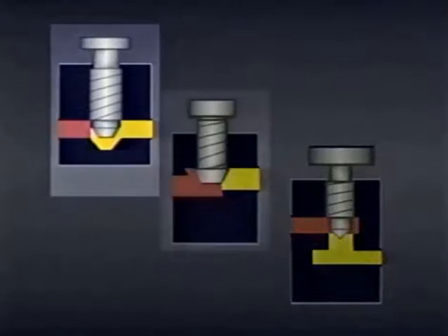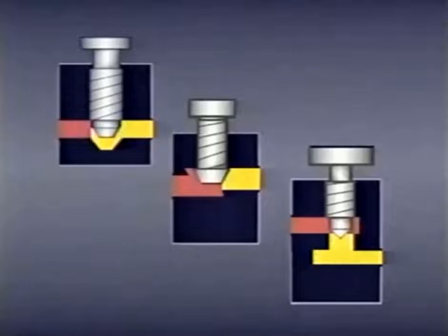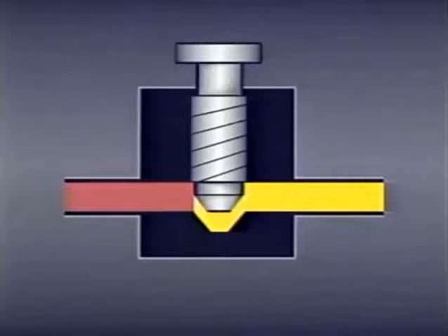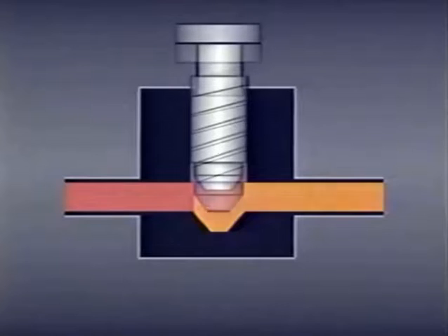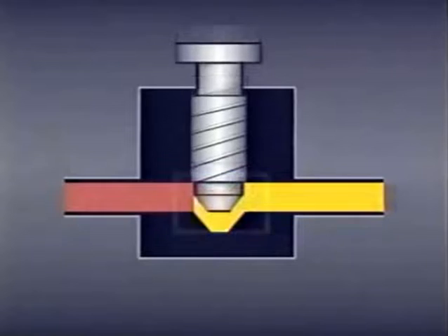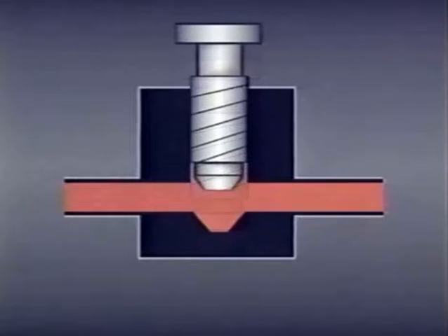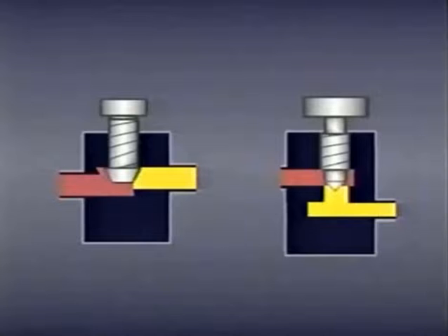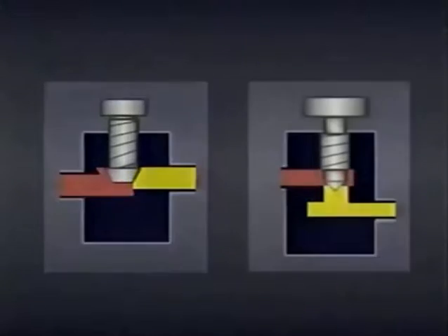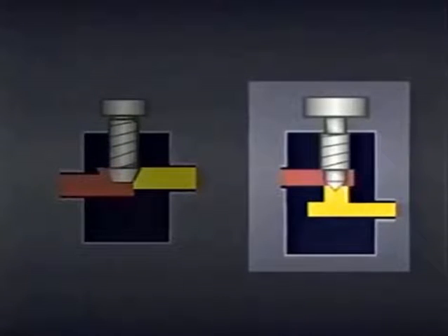Gate valves, globe valves, and needle valves are all examples of variable orifices. A gate valve permits flow straight through its center. The size of the orifice is determined by the position of the gate. Normally, gate valves are used either to shut off fluid flow completely or to open the valve up all the way. When more than just on-off service is necessary, globe valves and needle valves are used. Of these two, needle valves provide the most precise and controlled adjustment of flow rate.